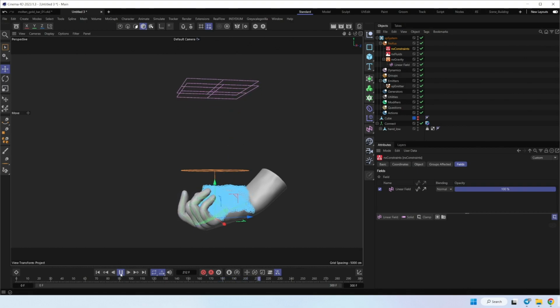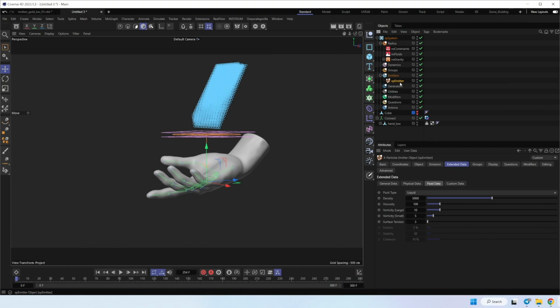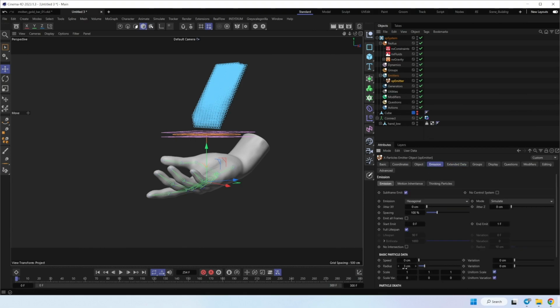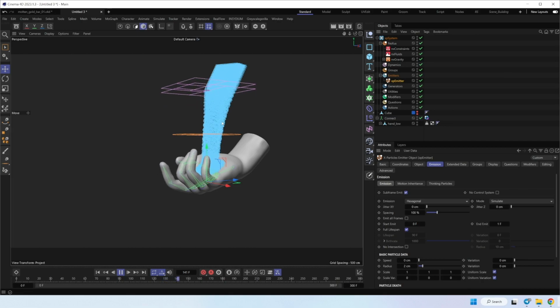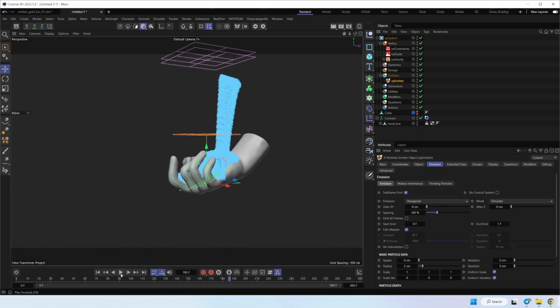You can add more viscosity to your setup. So next one, let's try to add more particles to the setup. Maybe it's two size. Also, keep in mind, if you change particle size too much, your simulation can look different. Not too much, but it will be changed because you have more density. As you can see, now it's much better following the shape. Yes, that's worked nice.